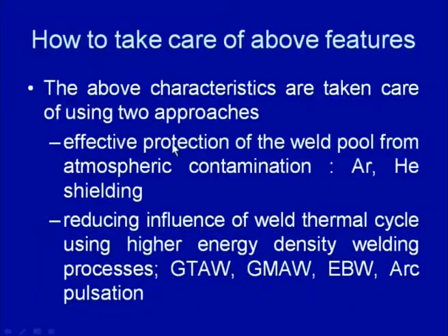One is effective protection of the weld pool from atmospheric contamination, and for this purpose helium and argon gases are used to seal the weld pool, so that the effect of atmospheric gases on the weld pool can be reduced. And another is, since most of the problems are related to the differential expansion and contraction and the differential weld thermal cycle experienced by aluminum alloys during welding.